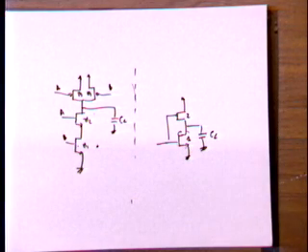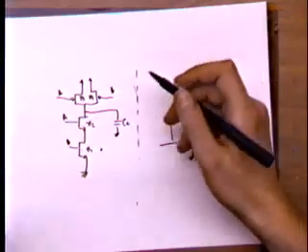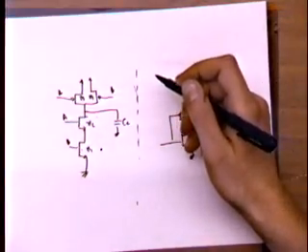So just for your convenience, this is an AND gate, so it's equivalent to the gate on the left, the gate that I'm highlighting right now. This is the resistor model of the NAND gate, okay? For these first times, it's probably useful for you to think about it in terms of resistors, but you will see as you go on and on, you won't need to draw the resistors all the time. You will just look at the gate and you will know by inspection what the right sizing is. Or at least you are expected to be able to do so by the end of the class.